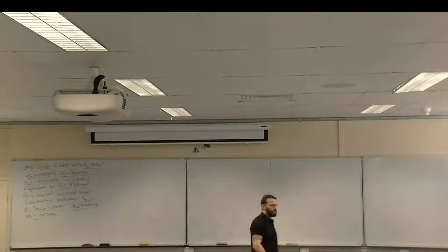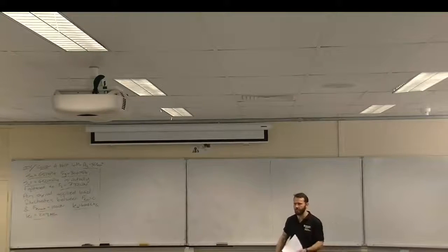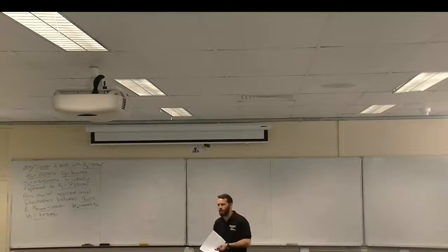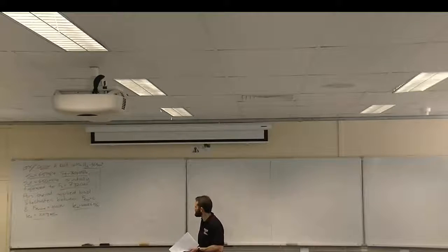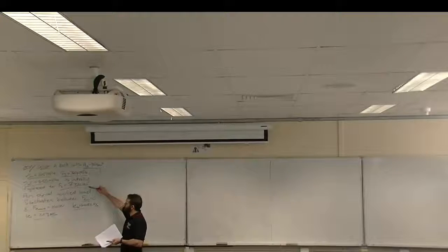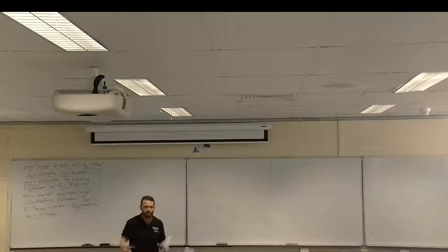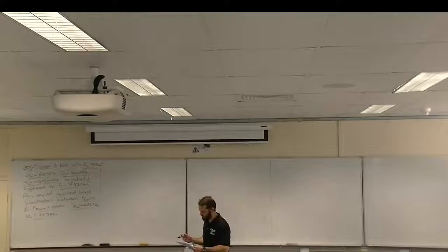Alright, so you've given pretty much everything. This is the sort of stuff that you need to interpret out of some sort of a drawn problem. So what does the load fluctuate between, what are the K values, what's the bolt size and material and all that kind of stuff. It's all axial load as an initial given, okay? So in this case, initial tension is given, but you can work out what the actual stress value of that is just by dividing that by the area anyway. I think it was like 90% proof load or something like that.